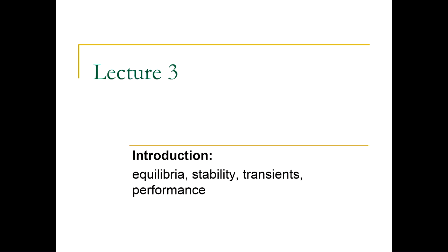So what was the conclusion? All right, so that's a very detailed answer. So open loop, is it better than closed loop? No. For what reason? Doesn't handle disturbances, model uncertainty, and things like that. So we will stick with closed loop most of the time in this subject. And we said open loop has its place, but feedback does help in terms of uncertainty.